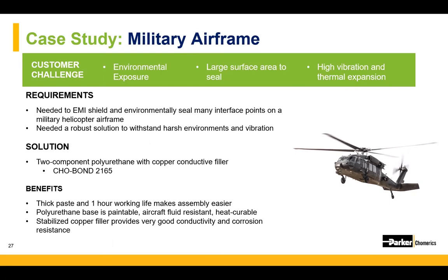So the 2-component polyurethane binder with a stabilized copper was a perfect solution. An added benefit was that the polyurethane developed full material properties in less than 4 hours with an elevated cure schedule. So the aircraft downtime was significantly reduced. So yeah, this was a good application.